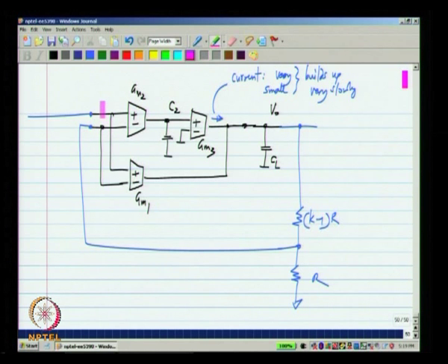If you have a given voltage here, if C2 is very large, it has to charge up slowly and this current builds up very slowly. The current magnitude is very small in the Laplace domain, but if you have a step input between the inputs of the op amp, the current here builds up very slowly, that is what it means. So, that is the meaning of having a very low frequency 0.